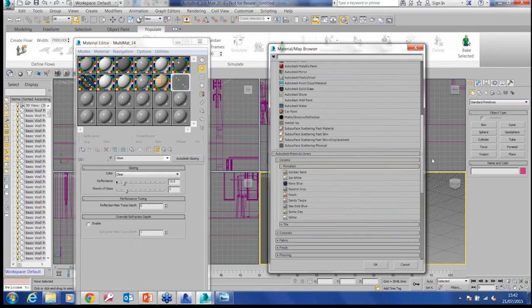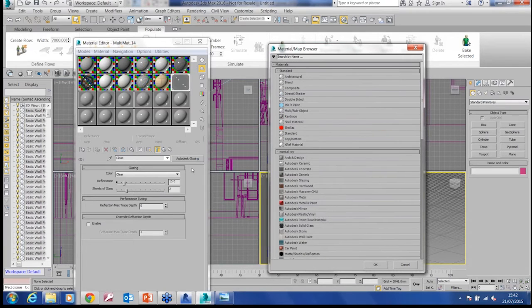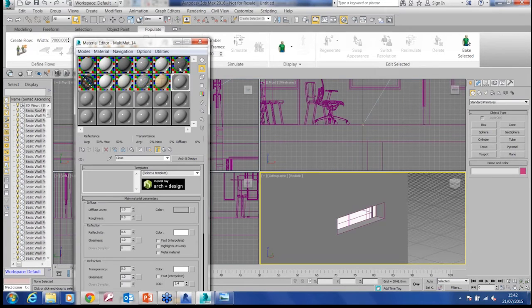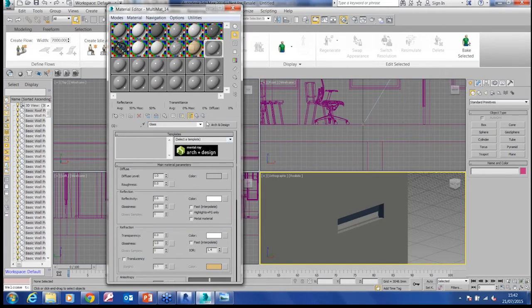I'm actually going to change this to be, rather than one of the Autodesk material libraries. So whenever you're using an Autodesk product now, the material libraries are common across all products. The material library you use in AutoCAD is the same material library that you can use in Showcase, Inventor, Revit, and 3ds Max, and it means that there's a compatibility between the materials across there. Okay. If I want to, though, once I get into here, I can start to utilize the Arc and Design materials. So these are a slightly higher res material.